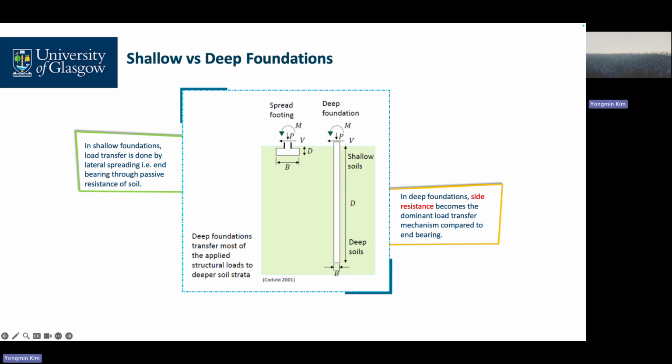What about the B? This B is only 1 to 2 meters. Compared to your pile length, this one is very small. So we remove this term. I don't care about how large it is in terms of diameter. We ignore this effect. So in our deep foundation bearing capacity, we only consider these two terms, cNc and qNq.